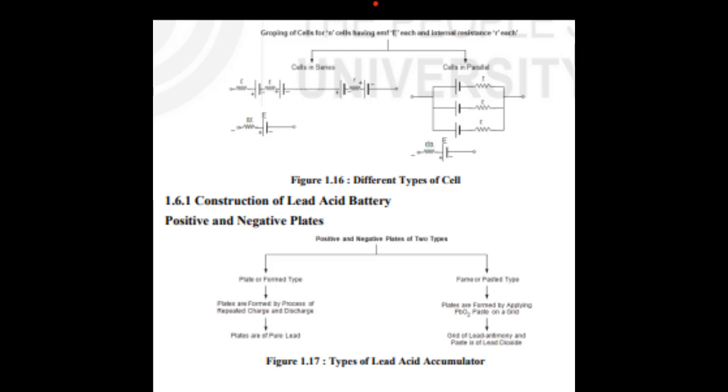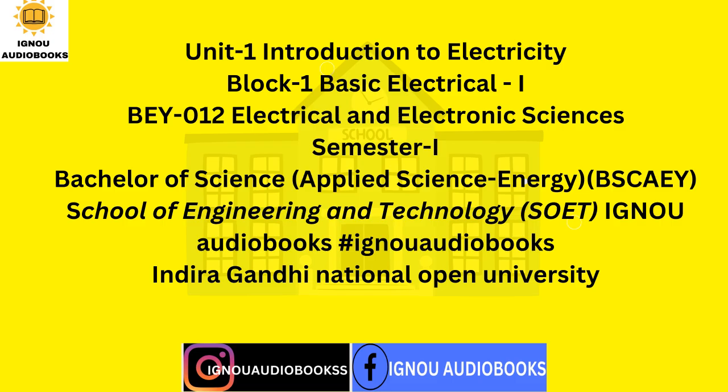1.6 Batteries. A battery is a collection of two or more cells. A cell is the smallest unit of a battery, which converts chemical energy to electrical energy. A cell always gives DC voltage, EMF, and DC current. Cells are of two kinds: primary cell and secondary cell. Primary cell. A cell based on irreversible reactions, whose components must be renewed, or the cell itself replaced when it is run down, is known as a primary cell, e.g. simple voltaic cell, Daniell cell, Leclanché cell and dry cell.